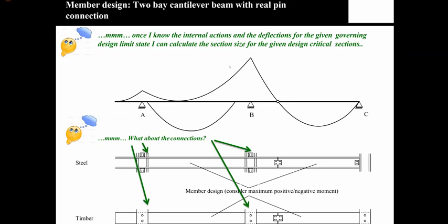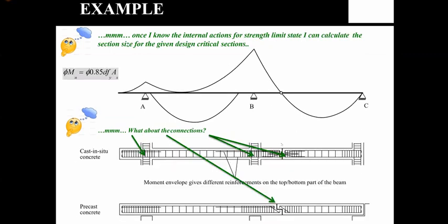For example, if I have to design a concrete beam for the same problem, and it's a cast in situ concrete beam, I want to achieve that hinge behavior so that there is no moment transfer. How do you achieve that? By truncating the longitudinal top and bottom bars and introducing coupling bars, which are diagonal shear bars, so that they just transfer the shear but they don't transfer the moment, right? And these are the basics.